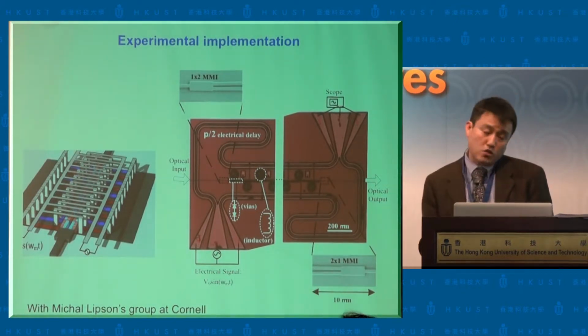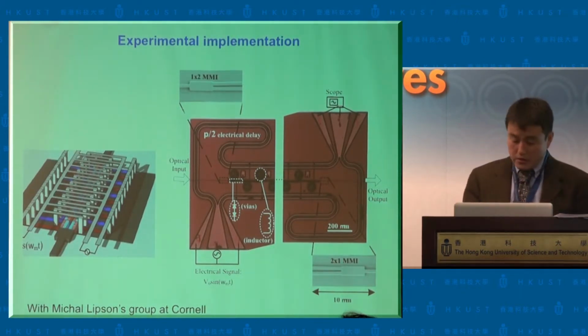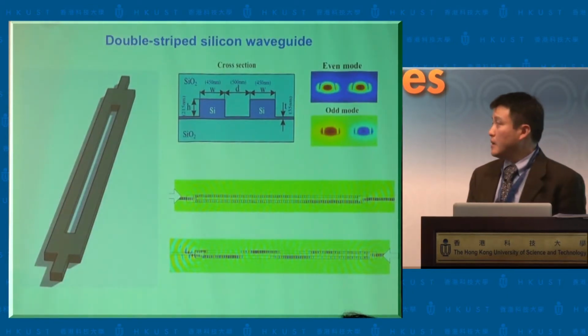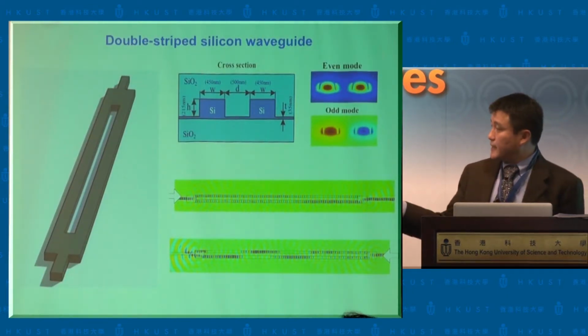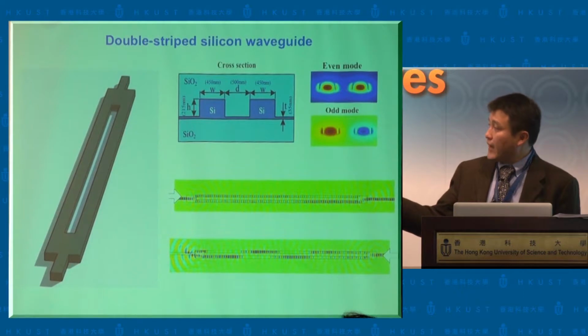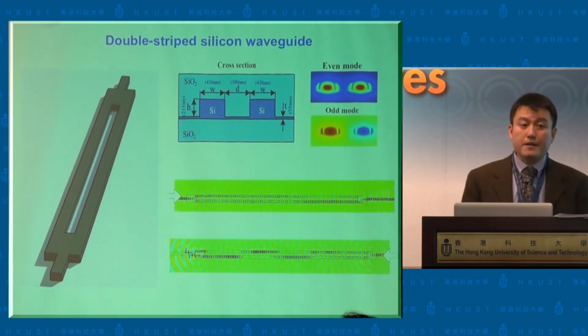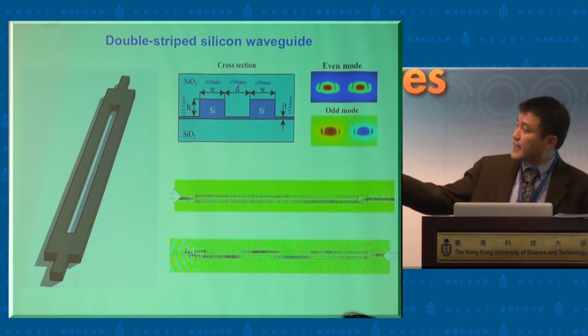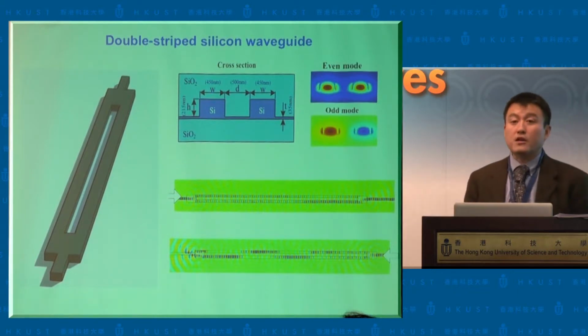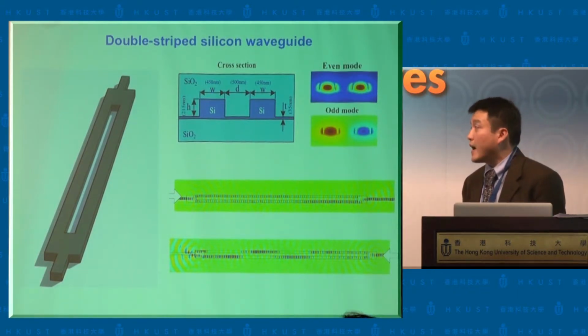the right modulation pattern. So the optical part of the structure basically consists of a waveguide through a multimode interference filter, coupling to a 2-mode waveguide and then coupling back into the single-mode waveguide. This 2-mode waveguide section here is where we do the modulation. So it consists of 2 silicon waveguides.